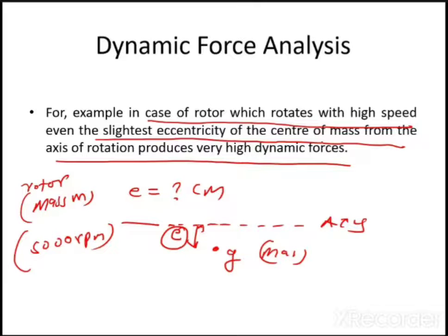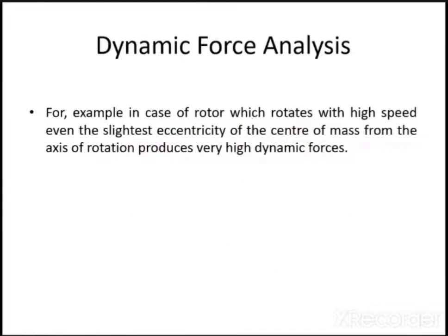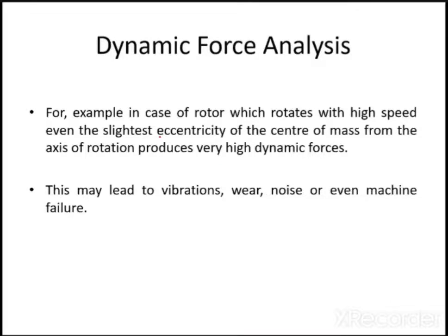And if you are not designing properly, if you are not taking care of these dynamic forces, can anybody tell me what may happen? In case of this rotor, if you are not doing the dynamic force analysis, and the eccentricity is produced, that is, the axis of rotation of the rotor and the center of mass of this rotor have some eccentricity, what will happen? The vibrations will be there.